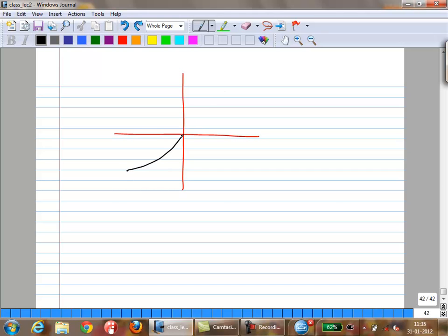something like this, let's say. So ideally you want to be operating here, okay, but this offset could push you somewhere where it could saturate the output is what I mean. Okay, so your output offset could be large enough where it could take you into the nonlinear region of the amplifier, which you don't want. Okay, so now that means it may be better to look for a different technique. So the other technique is called input offset storage.